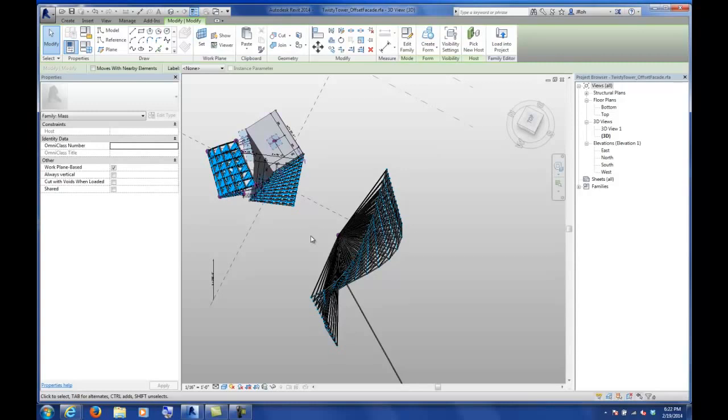Okay. Definitely. Just quickly, is the only way you could get this repeat command to work where you're skipping nodes potentially through Dynamo? If you wanted to skip every other node or something like that, yeah, it'd have to be through Dynamo. Or what I've done before is you cheat the system. You make two overlapping surfaces and divide the grid differently. You can offset the grid.